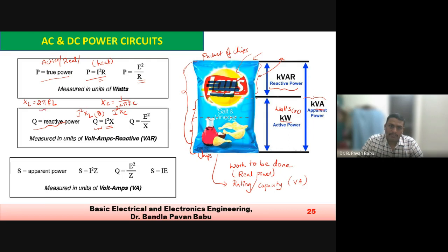Here 2 pi is the constant, and F is the fundamental frequency, or the frequency of the current or voltage of that particular element. For example, if this is the inductor, this is the current flowing through the inductor, and this is the voltage across the inductor. The voltage or current has a particular frequency, so there is some alternating component flowing through this element, and that frequency defines this value. L is the value of the inductor, in henries, and the unit of the capacitor is farads.